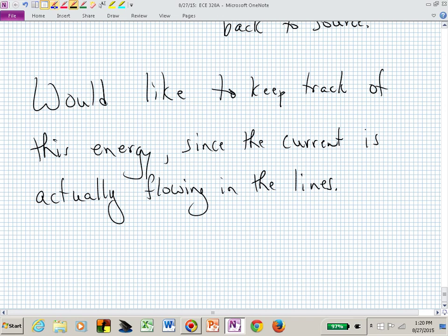Now, we've already used up average power, or real power. Now we're going to relate this. This is sort of in the opposite direction, sort of orthogonal to the real power, because it's not doing us any good per se. But all of the machines that maybe we have in our factory are inductive, so as far as the power company is concerned, you're not only a resistive load, but you have some reactive component.